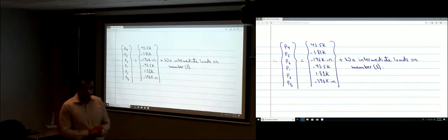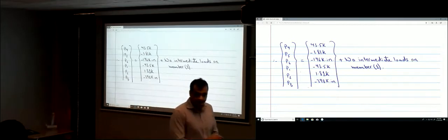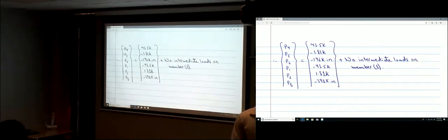Yes? So in your local equation, P equals KU, you transform the U in the global direction, right? When you calculated U in the first step, the step that you said you understand, you calculated U in the global direction. Now, you need to find the internal forces. The internal forces are in the local direction.